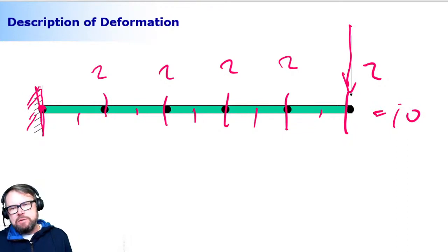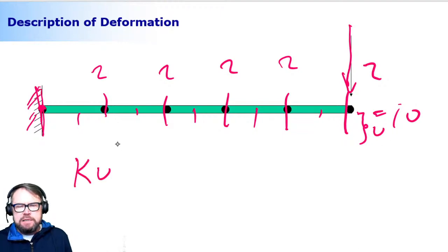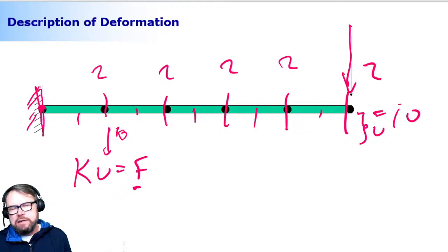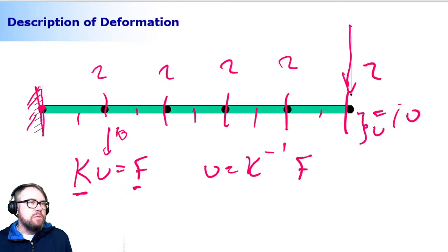Now what we could do here is solve the static deformation of this free end, this U here, by building the stiffness matrix, taking all these 10 degrees of freedom into account. This will be a vector that consists of 10 degrees of freedom. And then this will be the point force that is associated with one nodal degree of freedom. So this could be solved easily by inverting my stiffness matrix like this and multiplying that by a corresponding force vector. What we're going to get as a result will be each one of these nodal displacements. So this one here will have 10 unknowns, like I mentioned already a number of times.